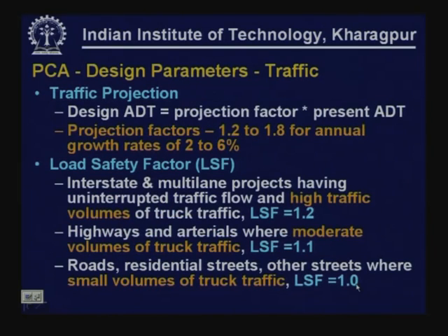The traffic projections are to be made in the following manner. Design ADT will be a projection factor multiplied by the present average daily traffic. Projection factors normally range from 1.2 to 1.8 for annual growth rates of 2 to 6%.